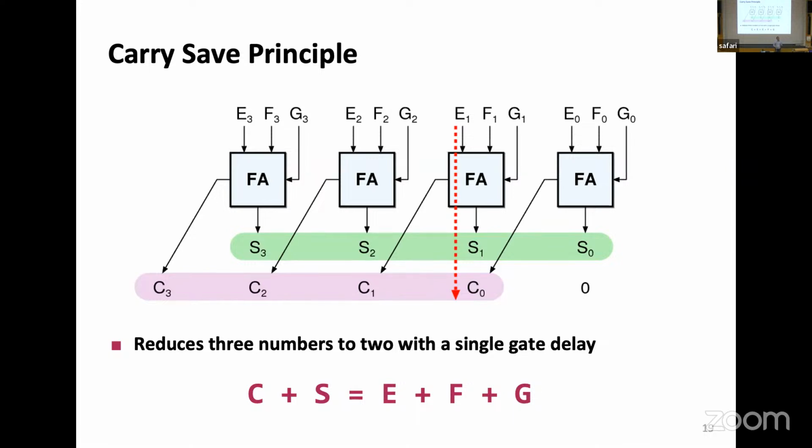So this is what I was talking about. We kick the problem down. The thing that slows things down is this carry merging with this sum, which potentially generates another carry that merges with this sum, and so on. That was the curse. If I'm just saying, you know what, let's save the carry, let's not propagate it, then I can do this in one very fast step. Okay, how does it help me?